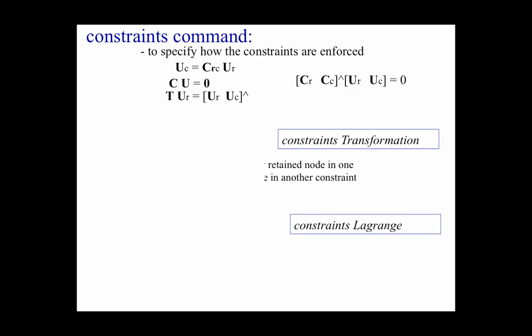So we're solving basically a slightly different system. You'll note that if you're using the norm of the displacement increment, you're not just solving for the displacement increments, you're also solving for some lambdas in there. Those lambdas are basically equivalent to the penalty in the penalty method to enforce that constraint. Those values turn out to be the same.